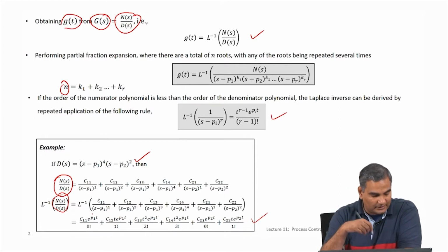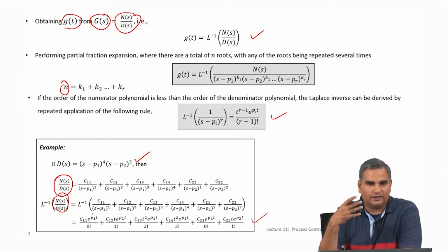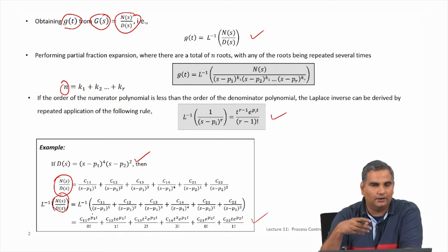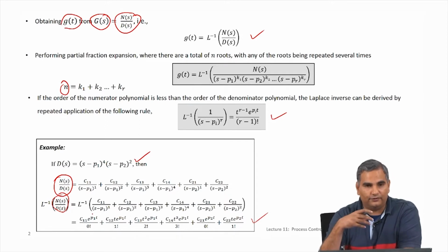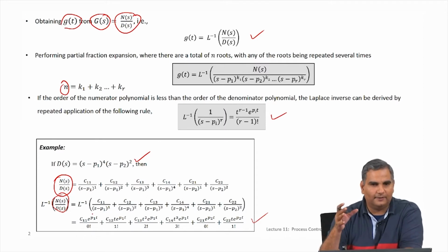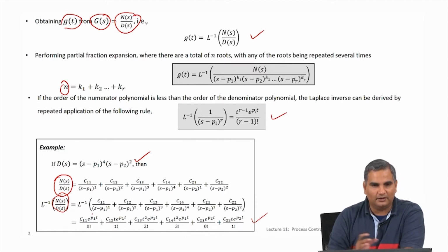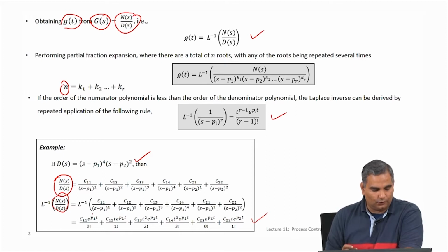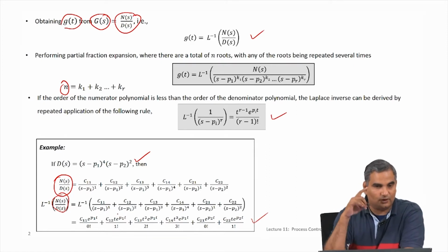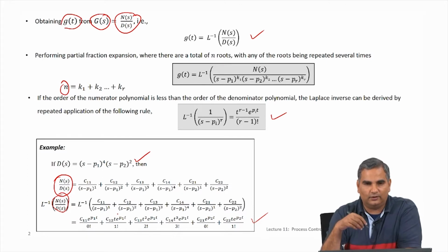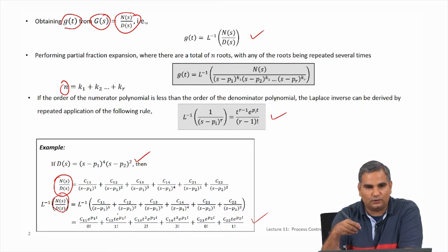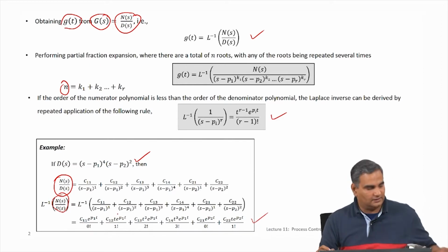So, what this partial fraction idea does for us is it gives us a conceptual framework to understand how this inversion is done. Then that will tell you how you can really think about stability of these control systems, performance and so on. So, you will see the power of this notion of partial fractions later as I teach stability in very simple fashion, because once you understand this, then the notions of stability become almost readily apparent. So, we really do not have to worry about these constants to understand stability. However, if you want to actually invert this and then do some computations, of course, you need to calculate these constants and see how they come about.